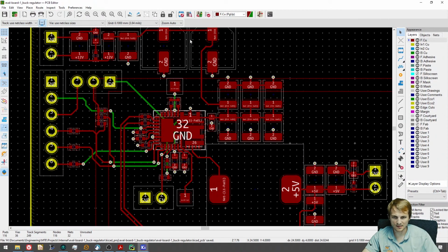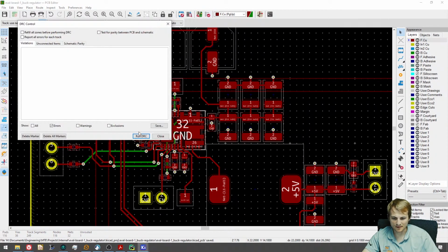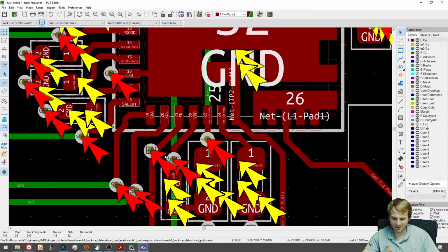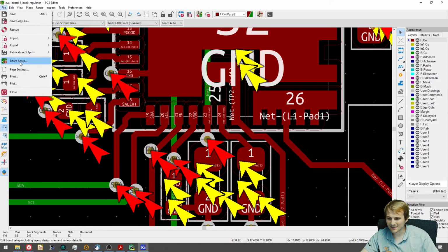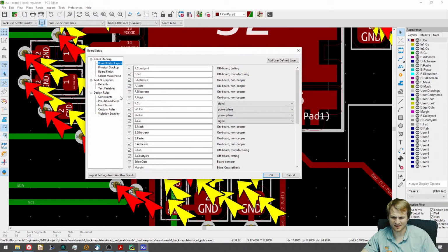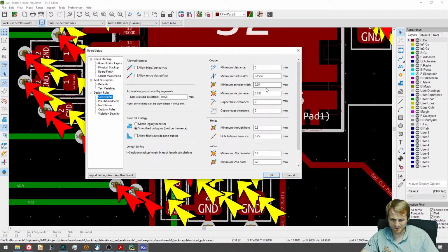And look at that. First cut of this is done right on time. Let's see what we get, DRC. Oh, boy. Oh, I used 0.25 for all of these instead of the 0.3. Outstanding. But I could have sworn I made the minimum 0.25. Oh, I never went back and changed this.